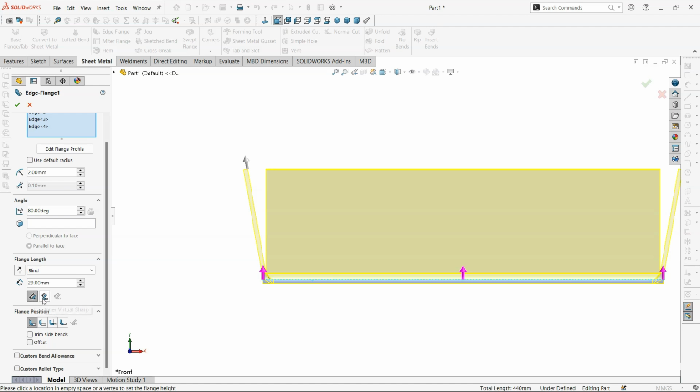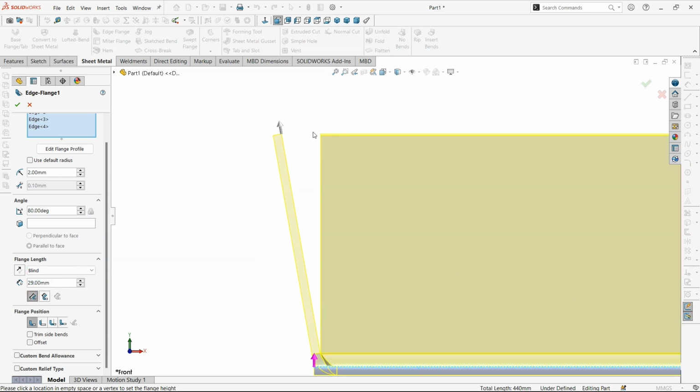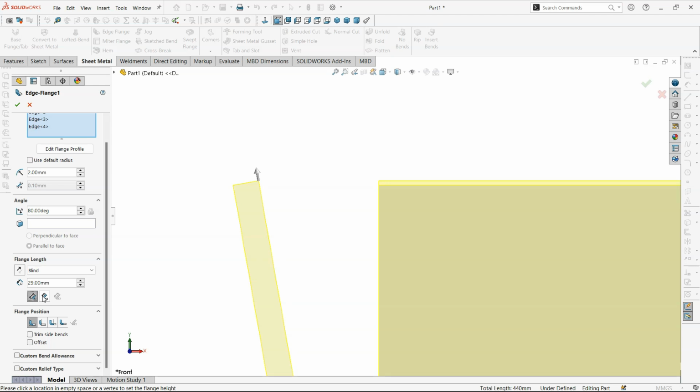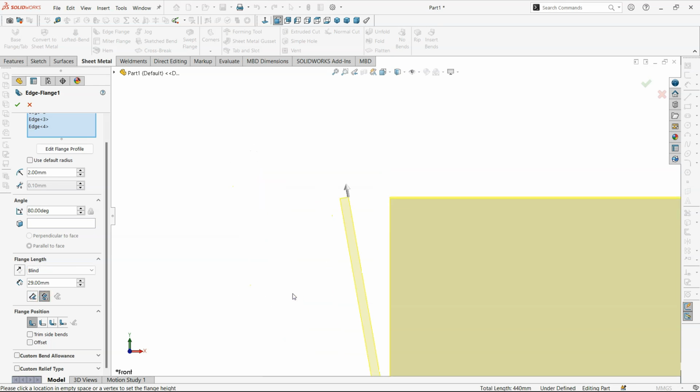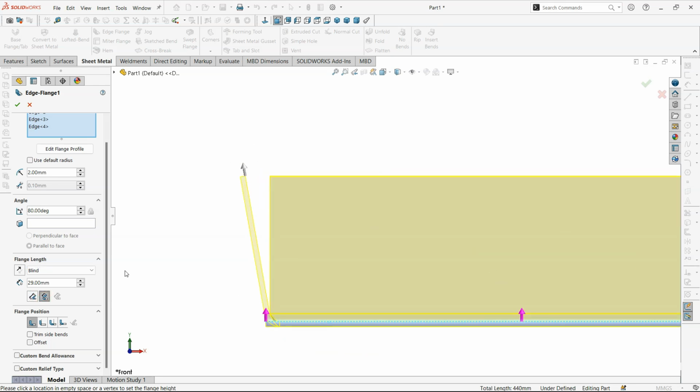And the second option here is the inner virtual sharp, which says that after the radius has ended, the length will be counted. So you see here, if I click this and I click this, there is a minor difference. If I zoom in and now I select this, the length will be increased. You see overall length is 29, but there is a difference. So that's what it means.